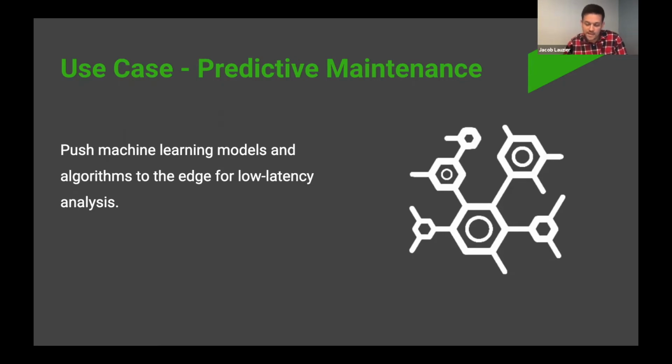One example of that at a customer of ours, we were able to stop the machine 45 minutes before a tool fails just by looking at high frequency load data, but being able to capture that information alongside a bunch of other very precise information about the tooling that's being used and how many parts are being produced. So we're able to develop these models in a way where we can have a very high level of accuracy, over 99% confidence in stopping the machine. That enables you not just to not scrap parts, but also run a tool all the way to failure.